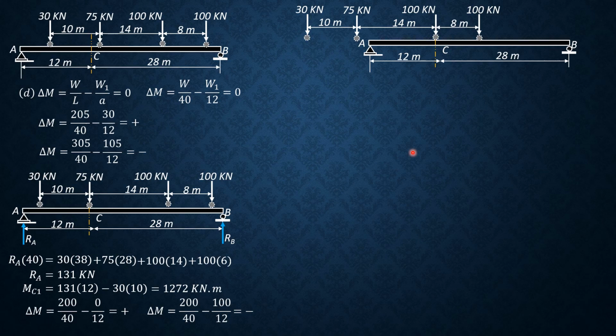Okay, let's position it and solve for RA by this position. Summation moment B equals 0, RA times 40. RA is 120 kilonewtons from the preceding position of the loads, or RA times 40 equals 100 times 28 plus 100 times 20.